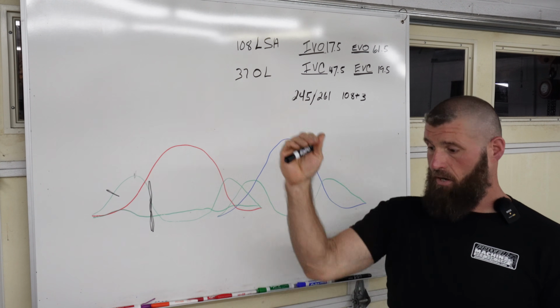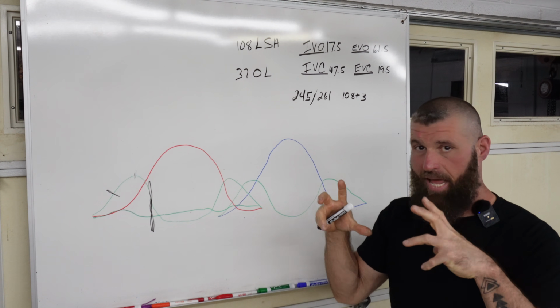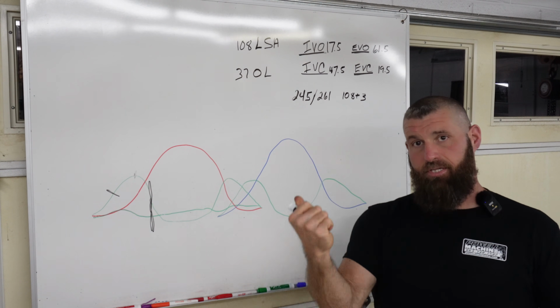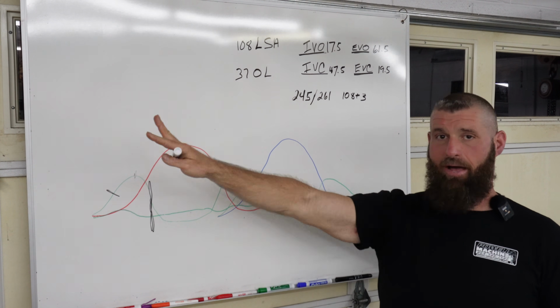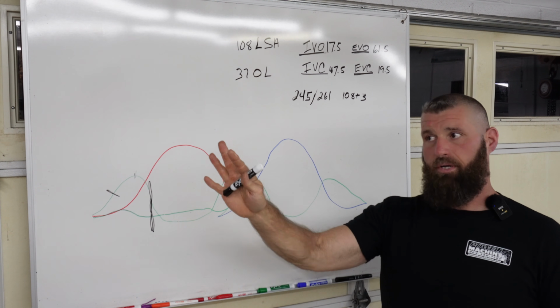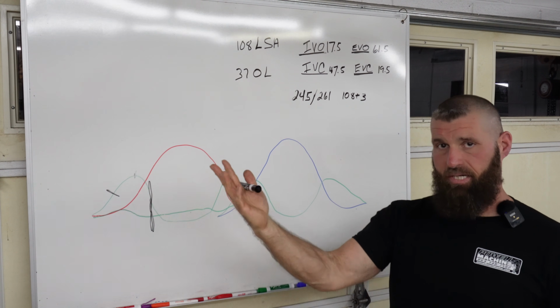The piston gets all the way to bottom dead center, and now the engine has to work to bring it back up. And as it comes up, it's pushing the remaining exhaust gas out the system, right? So that takes a lot of work. And not only does it take a lot of work, we call that pumping losses.